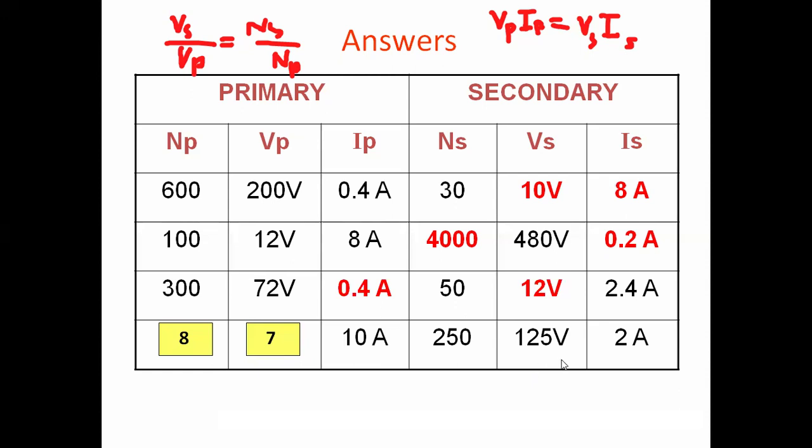It means the voltage must be stepping up. So let us see, the voltage in the primary must be less. So in this case, we know Vs and Is, we don't know Vp. So we will use this equation first, that is Vp Ip equals to Vs Is. When we use this equation, this is the current in the primary 10, and voltage in the primary is not known to us, and is equal to Vs 125 and Is 2.